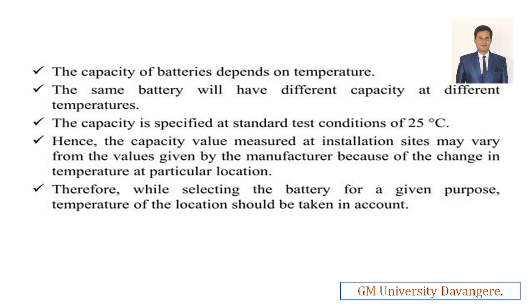Right, while selecting the batteries for any given purpose, please look after the temperature of the locations also, and it should be taken into account, right? Here in our state, the temperature may be very moderate. If you go to another state, especially West Bengal, the temperature will be more than 42 degrees centigrade. If you go to a place like Shimla, the temperature will be very low. So based on the regions, please try to select the battery ratings and also the battery for the purpose you're going to use it for, right.